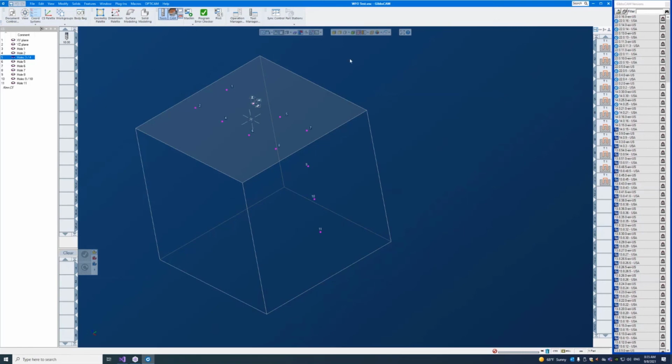Basically, we've changed work fixture offsets to be assigned to operations rather than being assigned to CSs. And fundamentally, that's the foundation of all of these changes. We think it's important to be able to assign different work fixtures to operations in the same CS, and also to be able to combine operations from different CSs onto a single work fixture. Those are both things that customers have asked for. I'll talk about some of the specifics about why and how as we go on.